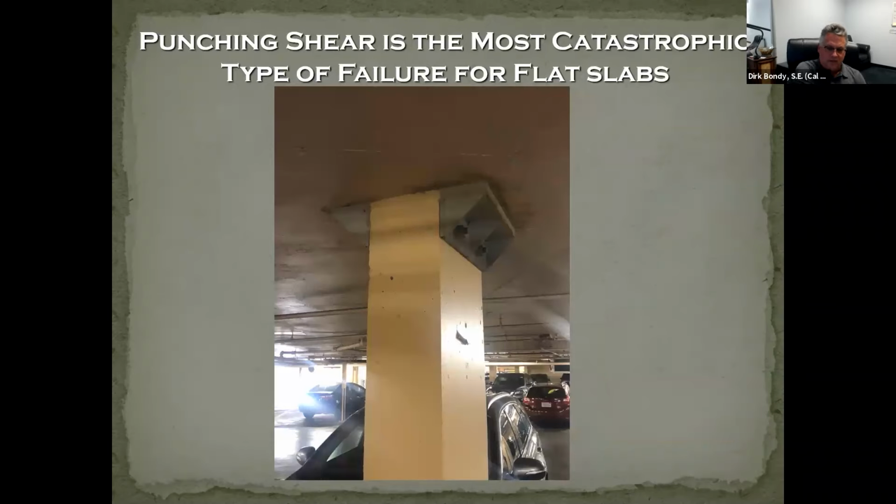This I can't emphasize enough. If you take nothing away from this talk other than this, you will have succeeded in learning something valuable. In this particular hotel, this was 2003, they had lost post-tensioning, and we externally post-tensioned the deck below this. It was a Holiday Inn at the time. It's something else now. But we got concerned about punching shear. I am always concerned about punching shear.